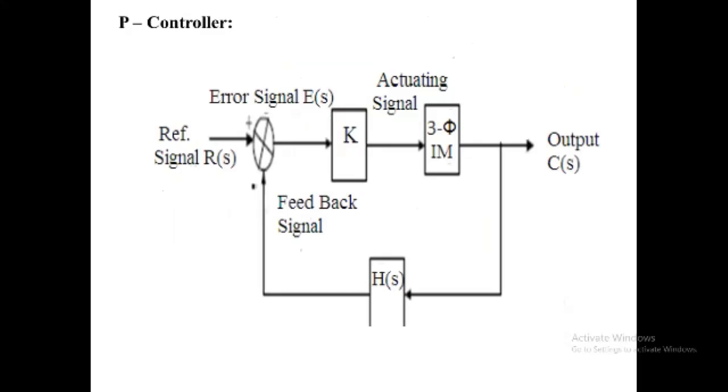Changing the controller gain K can change the closed loop dynamic. A large controller gain will result in a control system with smaller steady state error, that is better response following, and faster dynamic, that is broader signal frequency band of the closed loop system, and a large sensitivity with respect to measuring noise, and smaller amplitude and phase margin.